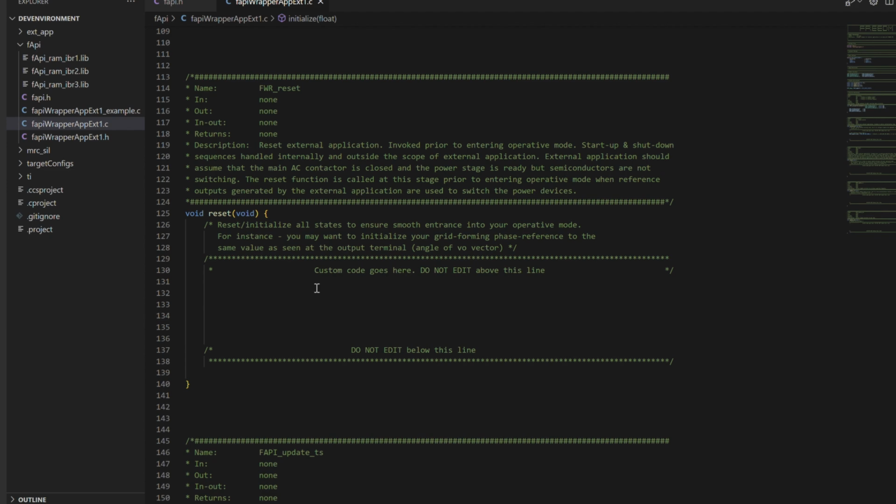It could be a TS rate or a slower timescale 1 millisecond rate. In the event when the inverter goes from operative mode to inactive mode, or when it's disconnected from the grid, the update of these control elements stops and the states are stopped at an arbitrary value. However, in this condition, the DSP, the control hardware, is still on. It still has power.